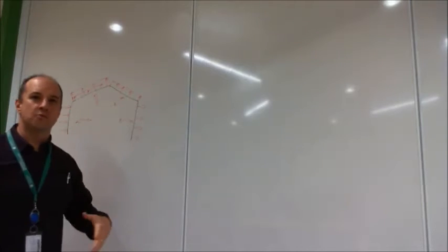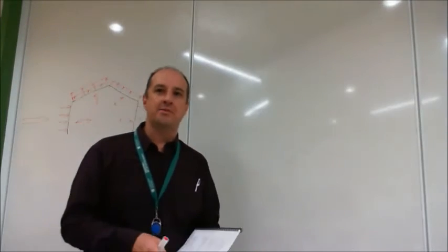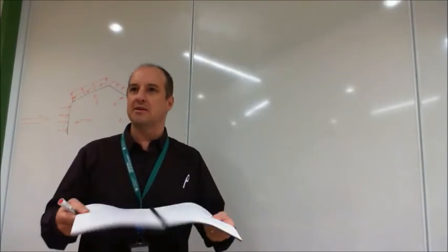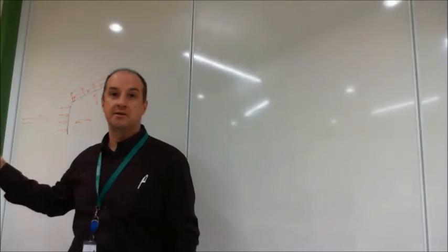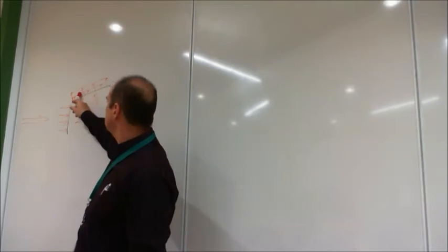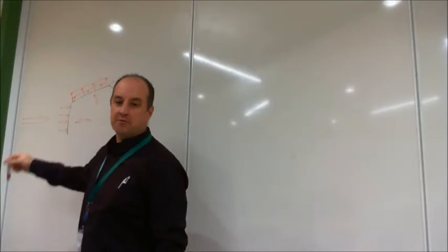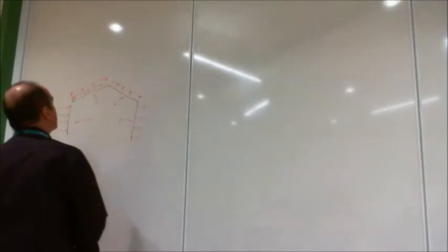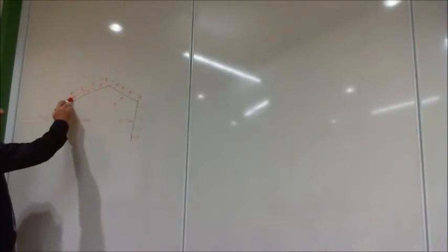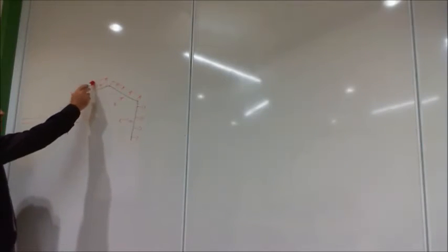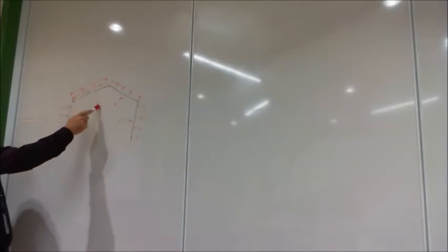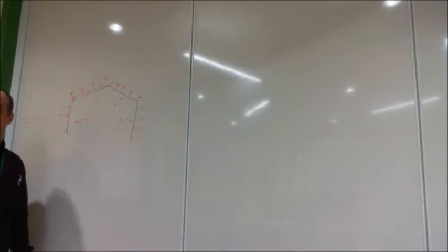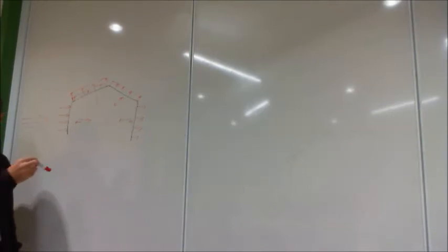And the basic reason is that wind, when it blows, it flaps. And you imagine a roof, you always see it kind of going up and down like this. And the force will vary between those two values. And it could be either of them at any time. And you can say, why don't you just give me the more severe one? The reason is, if you imagine you've got a suction, considering the case when you've got a suction force, and you've got this large force acting upwards, which counters it, you need to consider actually the smaller force, because that's going to be the more severe load case. Okay, I'll go through an example soon on this.